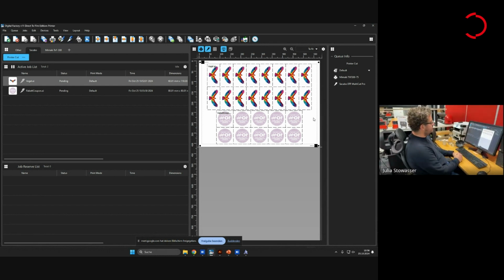That way it will be much faster, because if we create long cutting lines, the machine will be much faster compared to if we have just short cutting lines. So we recommend a length of about 500, 600, maybe 650 millimeter of length, and then do long cutting lines. In that way, the machine is the fastest.